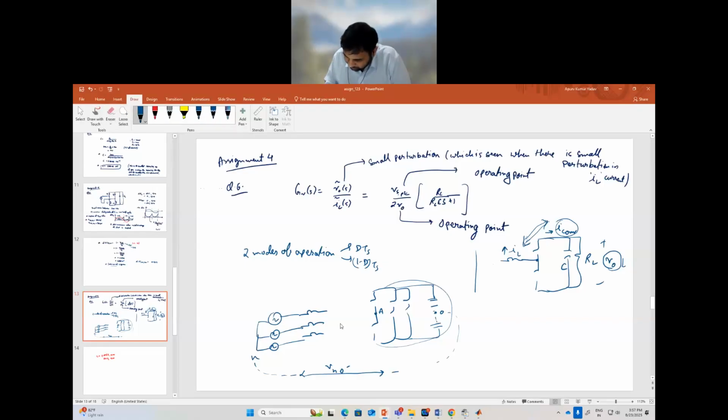And this VNO voltage is nothing but equal to the pole voltages VAO, VBO plus VCO at a given instance of time divided by 3. That DC voltage will come into the picture. If we look at this circuit, it will look like a sinusoidal source, then a DC voltage, which is a kind of common mode voltage, which comes across the N and O points.